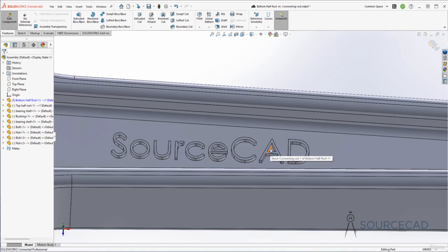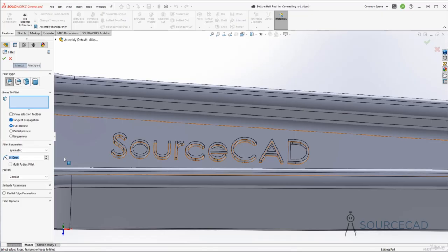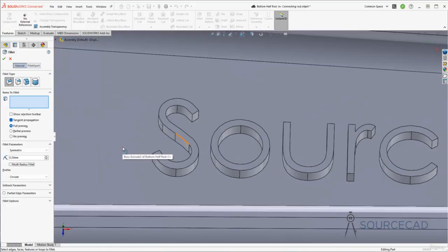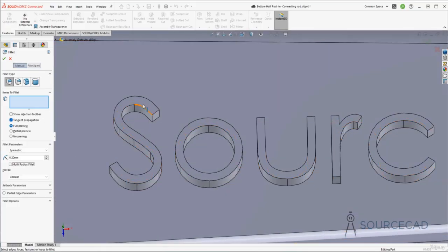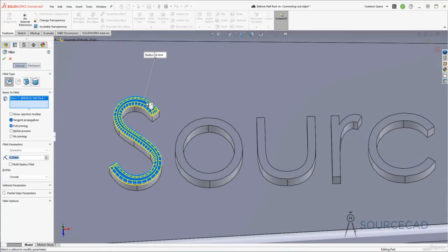Now also we can just make it finer simply by adding a few fillets. So let's do that. So go to fillet, and first I'll change the radius. So it is 0.1. Maybe I'll just make it 0.2 and press the tab key. And now to select the edges, well, I'll simply zoom in, and instead of selecting edges, I'll select the plane like so, and it will just select all the attached edges.